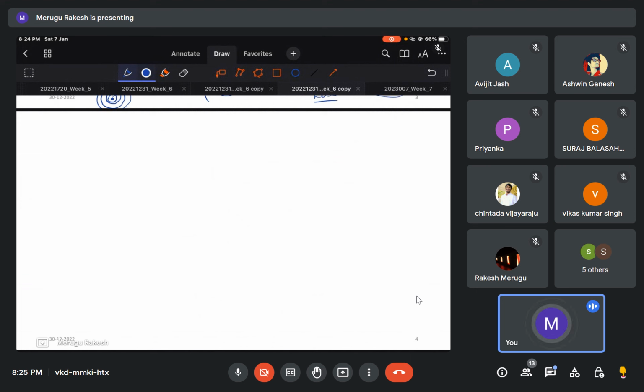The other option is not correct, since the go gauge is completely inserted into that product, and it ensures that the value is correct, whereas the no go gauge will not enter. So it corresponds to the lower limit of the shaft or whatever, but it does not exactly control. The other concept is that the no go gauge is a one parameter measurement.